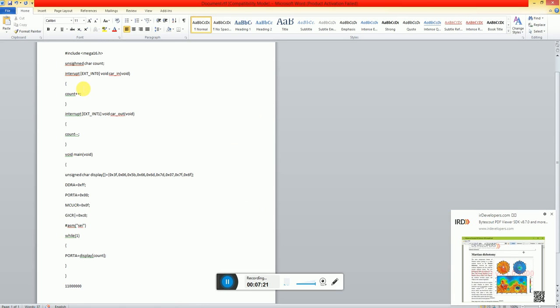Now, this AND was purposely used here because you don't want other bits to be disrupted, you only want to set these 2 bits. The values of the other bits would stay what they were initially or however they were initialized.